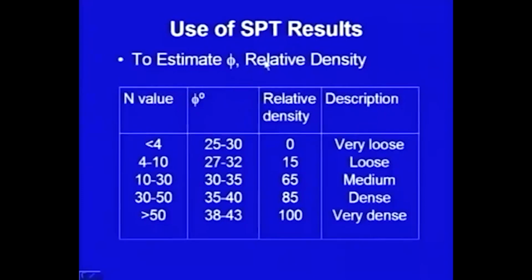How to use these results? SPT results are very important for sandy soils. In case of sandy soils, probably we have no other choice. You cannot take an undisturbed sample from a sandy stratum and test it in the laboratory. So, we rely on these tests. This test is very useful and it is used in design. So, you can estimate the phi value and also the relative density from the corrected N value.